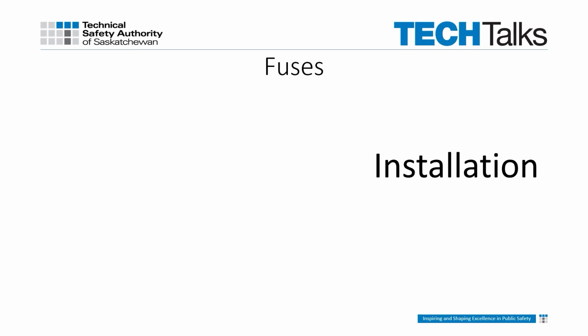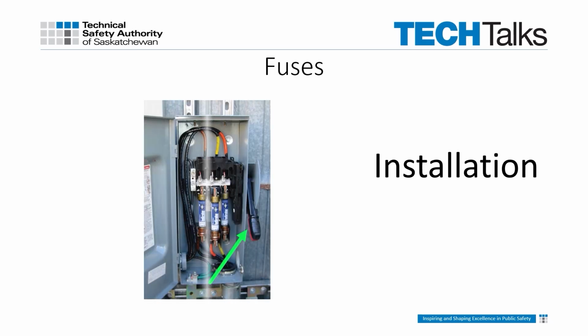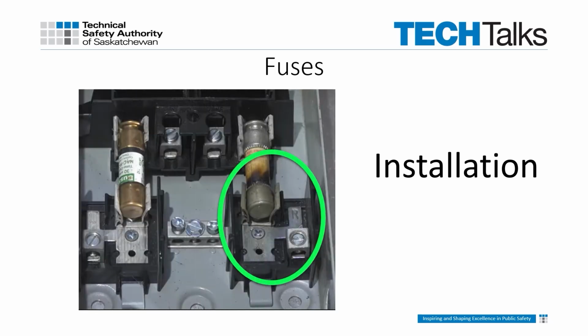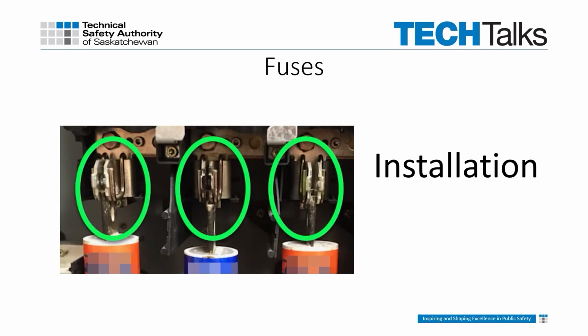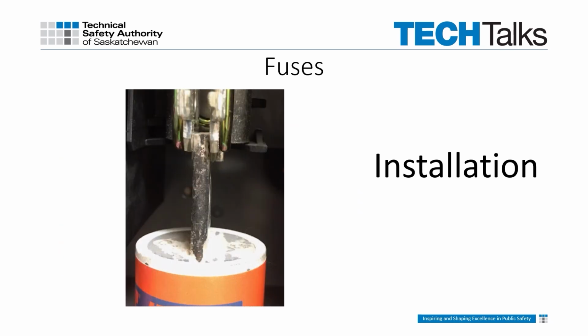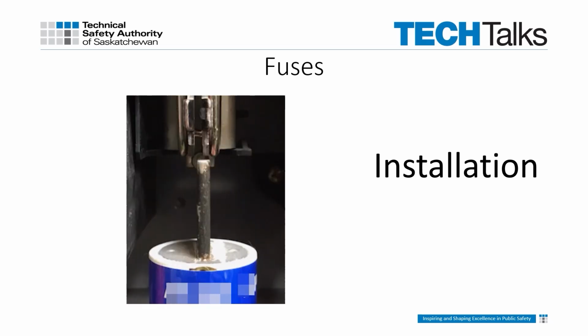Here are a few tips when installing fuses. Always de-energize before pulling or reinstalling fuses. Be sure to observe the installation. Look for discoloration as a sign of excessive heat or poor contact. Look for corrosion, which may hamper clean contact between the fuse and the fuse holder and may be a sign of future issues. When replacing fuses, the fuse holders should never be altered or forced to accept fuses that are not designed for such replacement. Finally, ensure solid contact is made between fuse holders and the fuse blade or end cap.